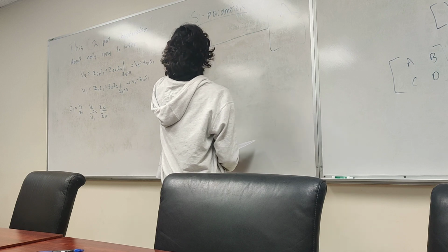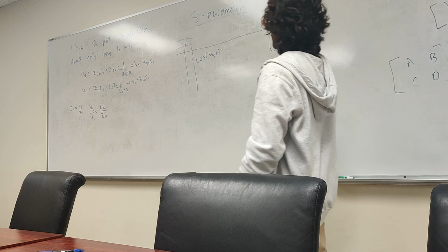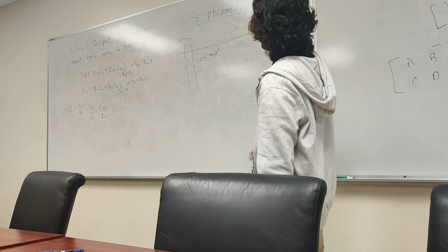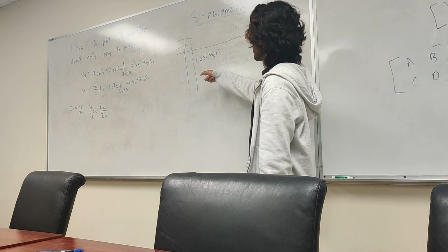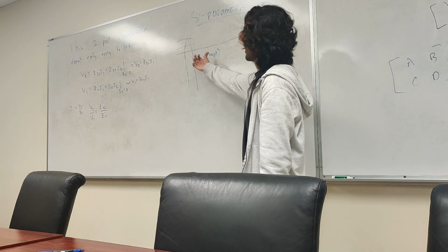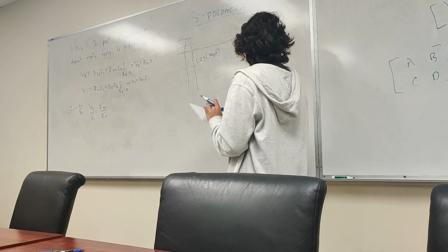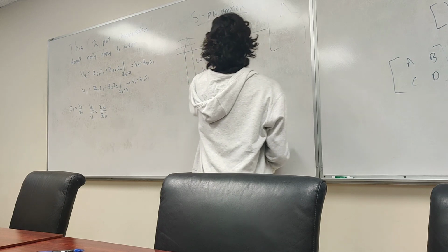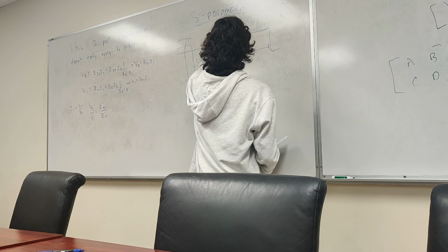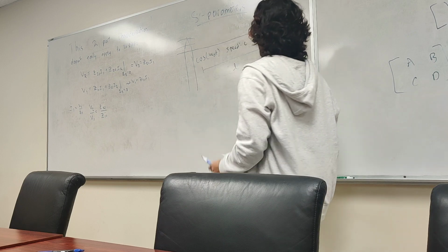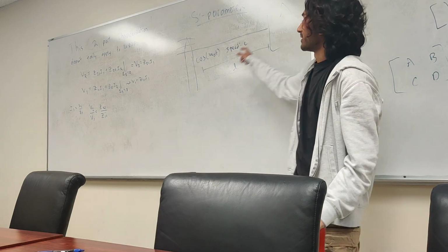Say we send out a signal here that's cosine omega naught t, a simple cosine. And of course, things don't travel instantaneously. It takes some amount of time to get here. That time is dictated by the speed this can go at. It's going to be an electromagnetic wave propagating through this, so it's going to be the speed of light. You can just assume that to be c. And it has to go across a certain distance of line here. Call that L. So we expect there to be some time delay between when we send this and when the house gets this signal.